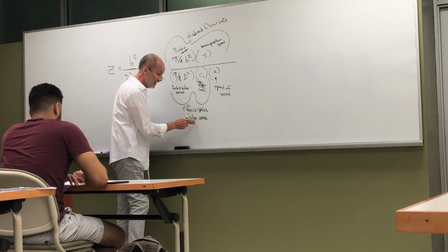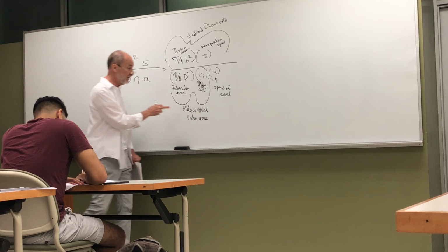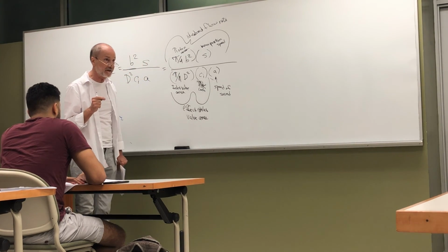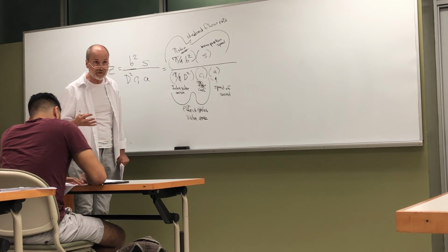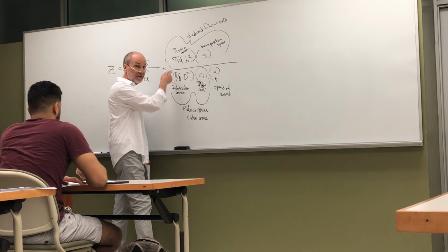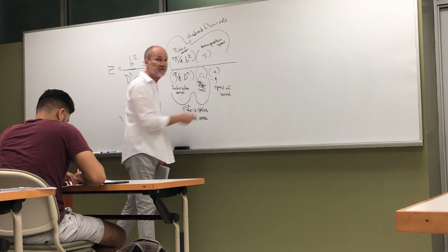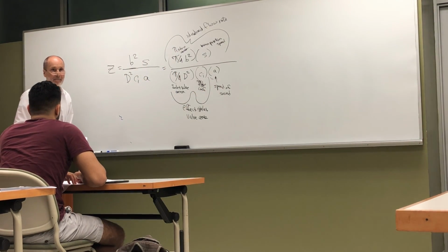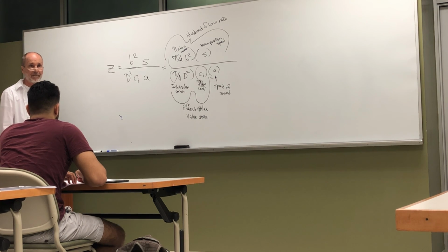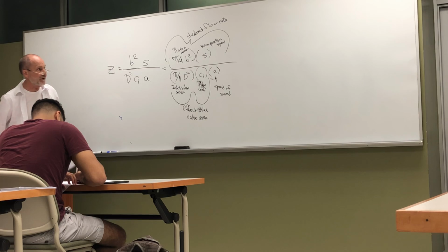Since this is the effective valve flow rate, this is the size of the valve, if it were isentropic, if it satisfied Bernoulli's equation, this would be the area. So I take the idealized flow and I divide it by the idealized area, I get the velocity, divide that by the speed of sound, and what do I got? I got the Mach number. And that Mach number increases with RPM.